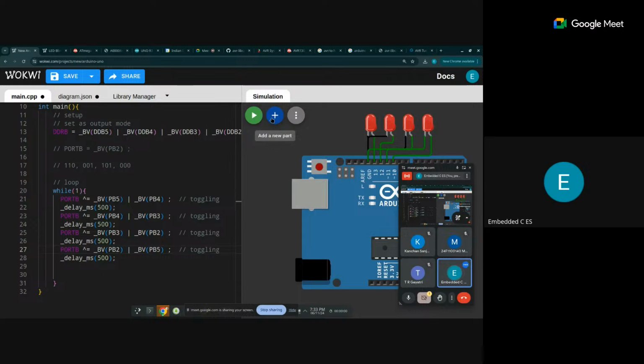So is this clear? Any doubts till now? How we are using GPIO and how those bits work, and about set, reset, and toggling. Toggling a single bit and toggling multiple bits, and setting multiple bits and resetting multiple bits. So this is the basic bit manipulation that we'll be doing in any embedded programming. So now we know that these kinds of approaches exist.